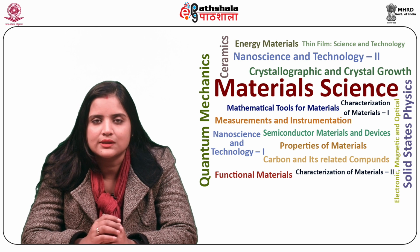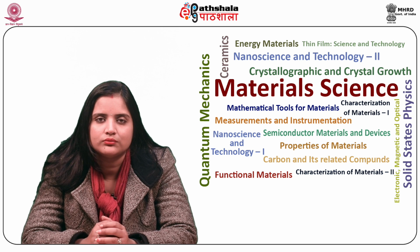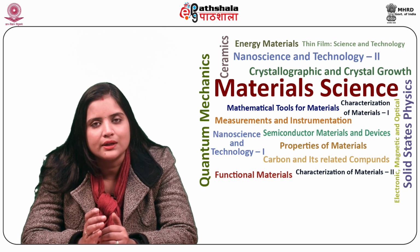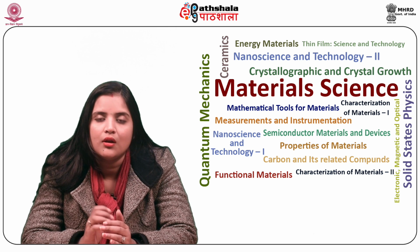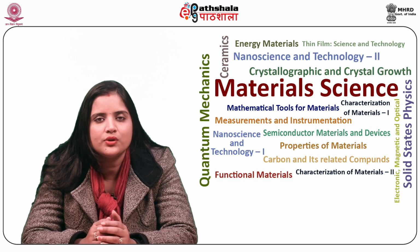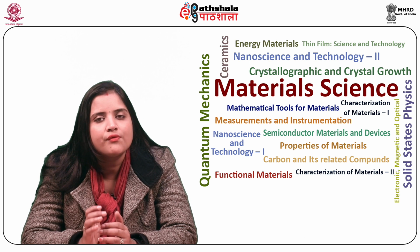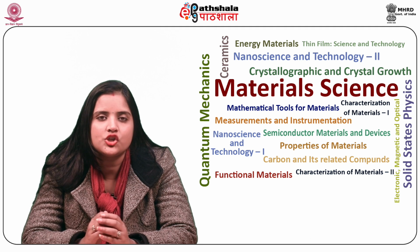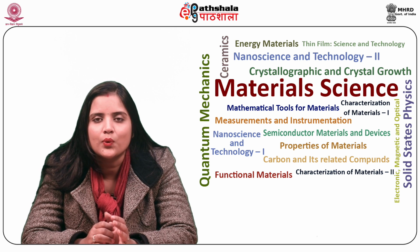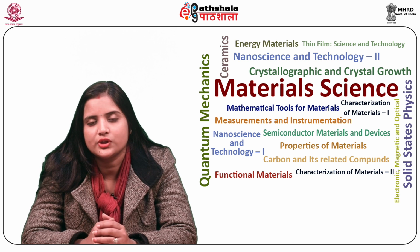Introduction of carrier gases increases pressure inside the chamber and it becomes 200 to 500 torr. Flow rate of carrier gas depends on structure of required nanomaterial because morphology of produced nanostructure greatly depends on pressure of chamber and flow rate of carrier gas. After achieving necessary conditions inside the chamber, gas flow and temperature of chamber are kept constant for deposition time.